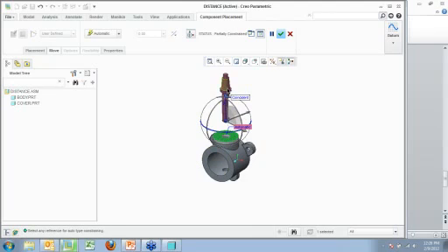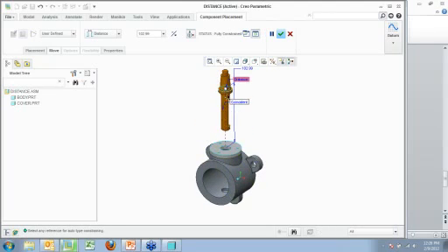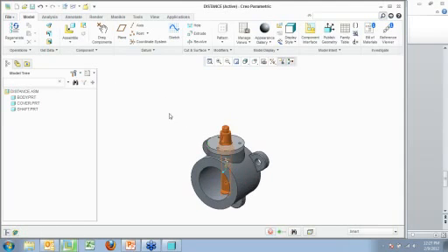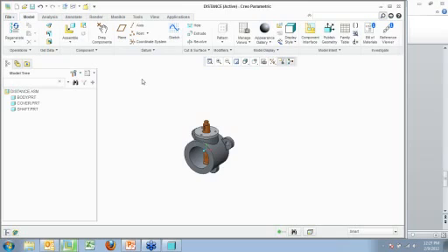So now let's go in and we'll select this surface and that face, and drag it down here. Notice it turned orange, and this is purple to show me that my distance constraint is the one that I just constrained, the one I'm playing with. Notice that my dragger disappeared. It's fully constrained, turned orange, so that now I know that this part is 100% fully constrained. That should be down there. So that's really useful for making sure that you do get things 100% constrained.